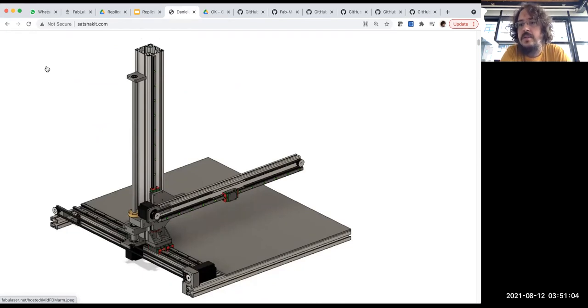The cantilever system hangs everything on a single arm, and the motion system connects all three axes together, X, Y, and Z, in a single arm. The challenge was that this system would probably cause many vibrations, so it needs to be well designed to be stiff enough to print reliably.